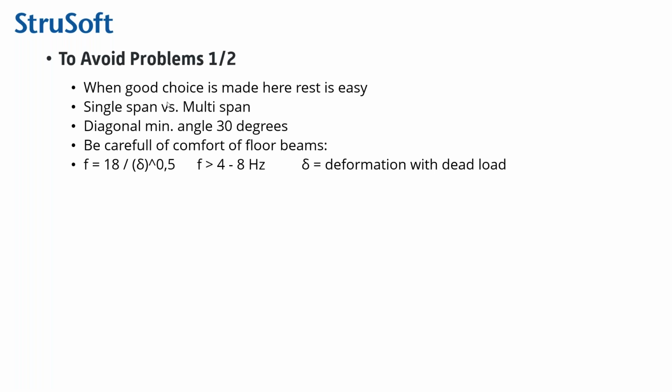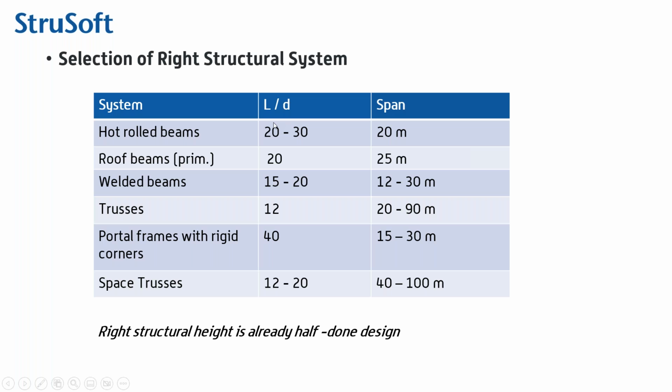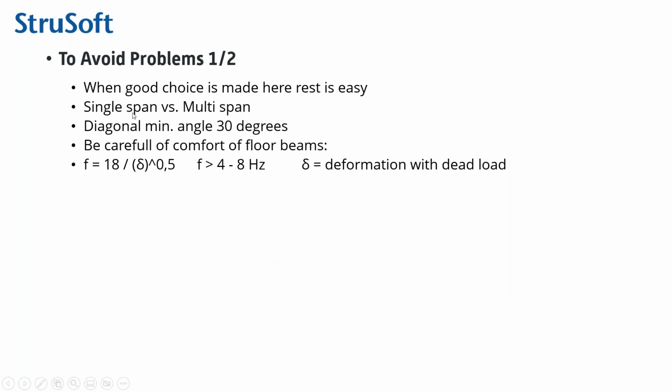Span to height, of course, if you have really high loading, it's a question about that. Is this recommendation load related? Absolutely, but mostly you select something related to this span to depth ratio, and then you just adjust the elements. Of course, if you have really high loading, you should consider reducing these limits a little bit. So it's not mainly load related, but partly, in cases of really low loads or really high loads, you can go below or over these limits if you want. But these are for typical structures, and you should obey these.